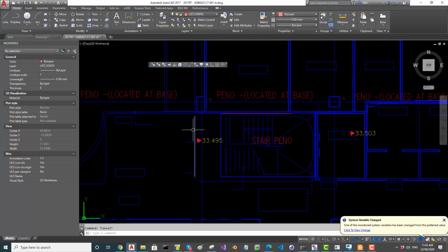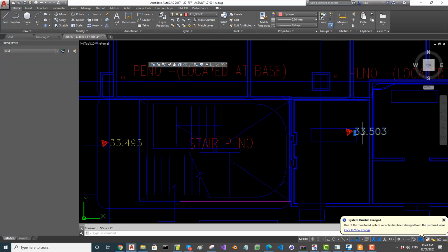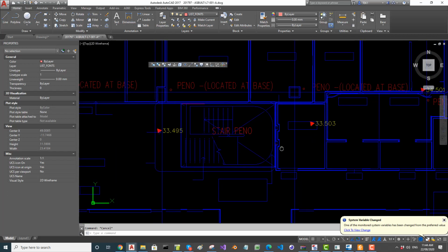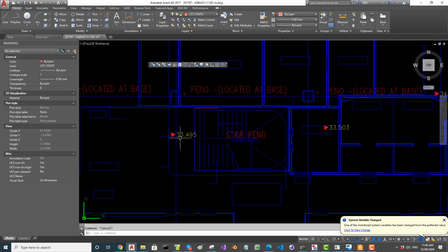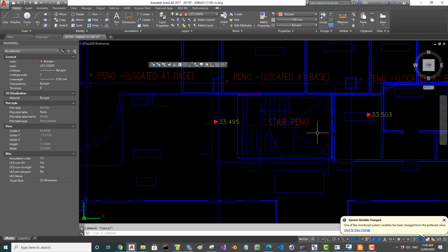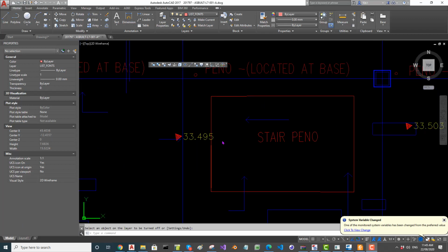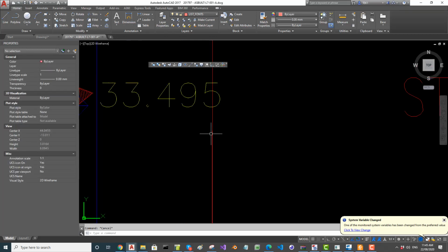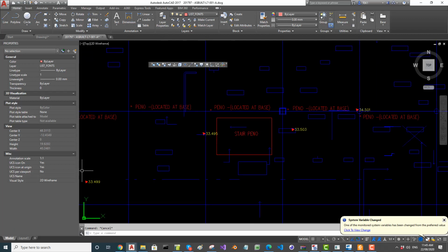Now checking the CAD file, I have got two RLs here, and this doesn't look like a site survey. It looks like they have brought in the architect's file and not really a site survey, so that becomes a question by itself. Where is the penetration in relation to the grid lines? We have to question that. I'm going to use the architect's value and the CAD values from here now. Alright, if I switch off some of the layers, I get one more line work here which says area boundary. So if I select that, say structure and area boundary, so I can possibly use that one.